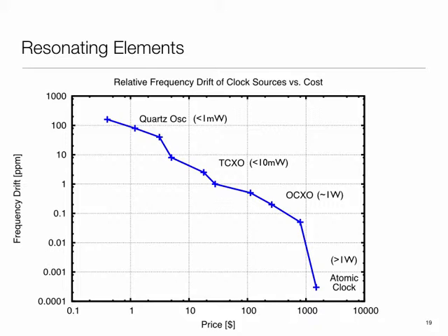So the question I'm asking is the following: in a normal platform, to save power while I'm in sleep mode, I would like to use a low frequency oscillator. What compromise am I making by using that? Precision? Precision in what? Yes, you are, because frequency corresponds to precision of something. What is the application level impact that you would see? Precision in short time, that's right.